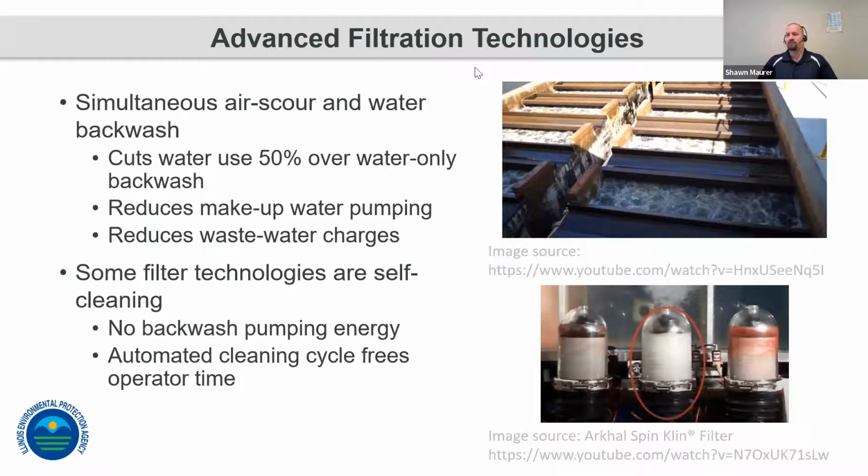And then there are newer filter technologies. The one shown on the screen here is a series of polymer plates that are pressed together. As particulates build up on them, back pressure builds up on that filtration, and it automatically kicks into a rapid backwash cycle that only lasts a couple seconds. Those plates can separate once that pressure backs off of them, and then flush out materials very rapidly, much faster than a sand filtration system. Something to consider with these is they do have some limitations on particulate size they can filter.